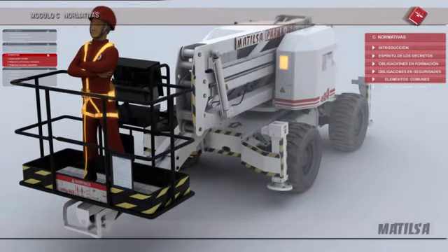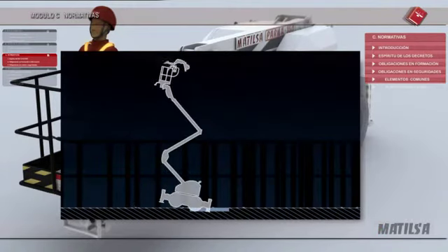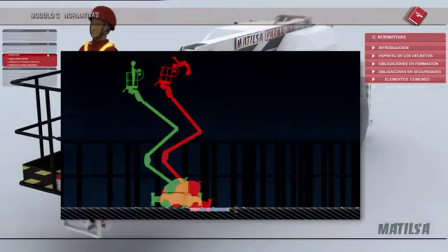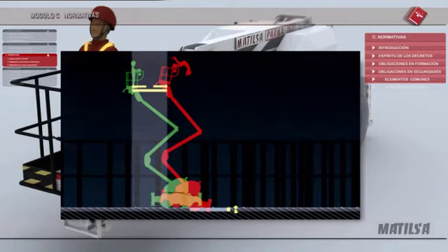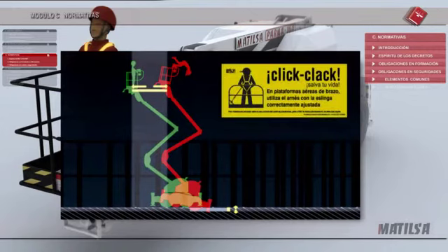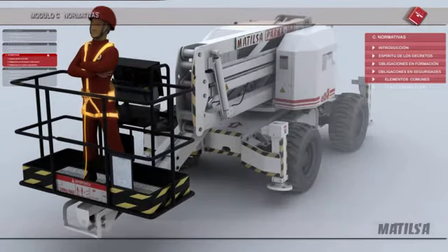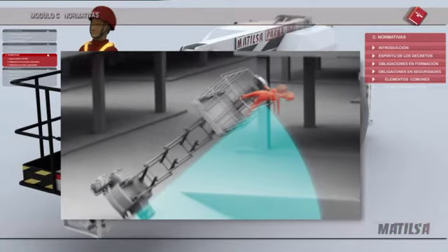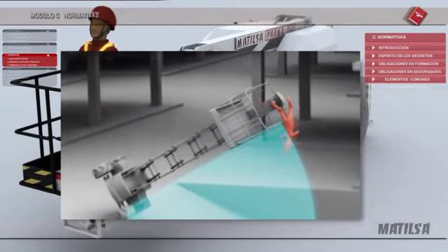If the access platform complies with the norm regarding the design and manufacturing, then its use is not compulsory. But its use is strongly recommended on arm-type platforms that could, by accident, overturn the basket or spill the worker out due to a crash or a blow. Nowadays, there is controversy among the renting companies, manufacturers and operators over its introduction also on the scissors-type platforms, since the most common accidents on this type of platform are due to overturnings. And it is possible that the worker might get tangled up with the harness and be crushed in the basket if the whole unit falls.